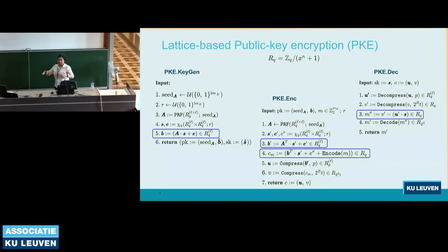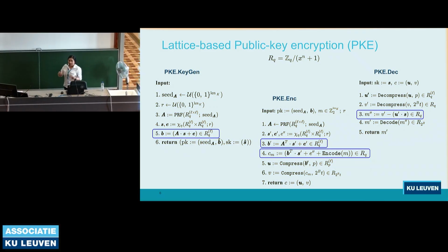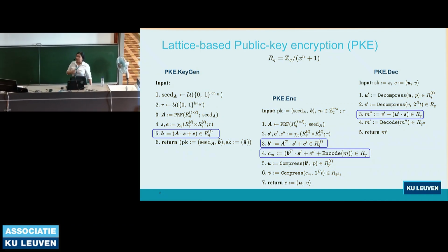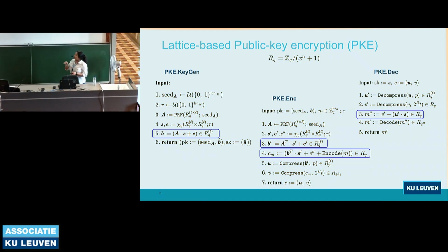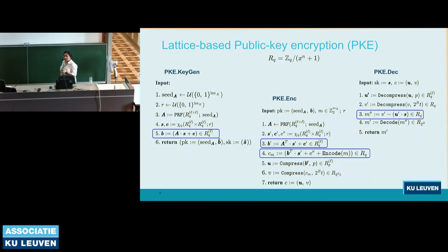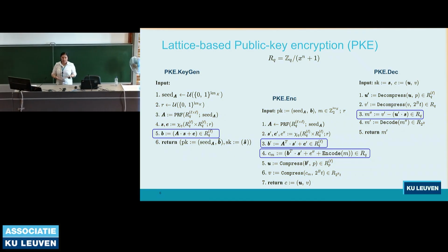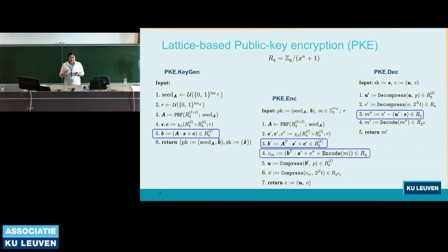Apart from the hash function that is used several times during key encapsulation and also here in the PRF, these polynomial multiplications are one of the most time-consuming and area-consuming operations used in most post-quantum key encapsulation mechanisms and digital signatures. So I will be covering mostly those multiplication techniques, how we actually implement them, what the process is, and the more specific instances which are used in several standards and many other candidate algorithms.